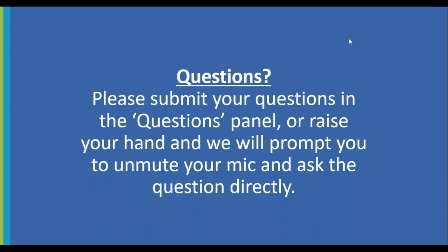Now, there is a question related to homogeneity. Samples can be potentially heterogeneous. Consequently, you want to have a sample that is significant for the type of study that you're doing. Increasing the mass of sample causes 2 things. It causes the experiment to last longer because you need to reach equilibrium at each stage with a higher mass of sample. And sometimes it becomes difficult to load that amount of sample as a volume, not as a mass, because it's a bigger sample physically.